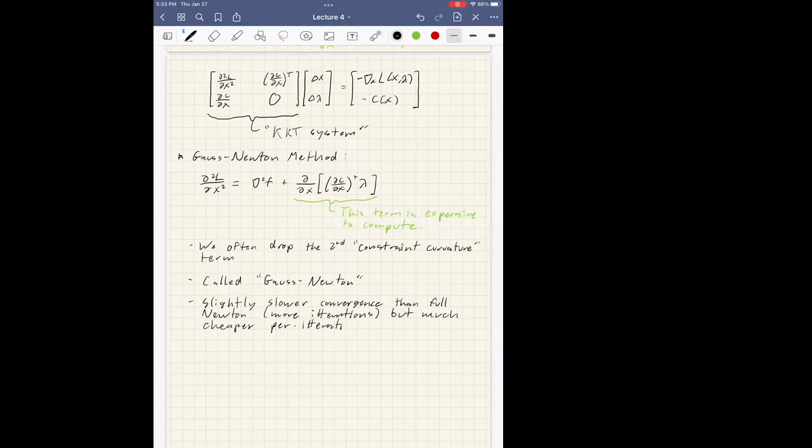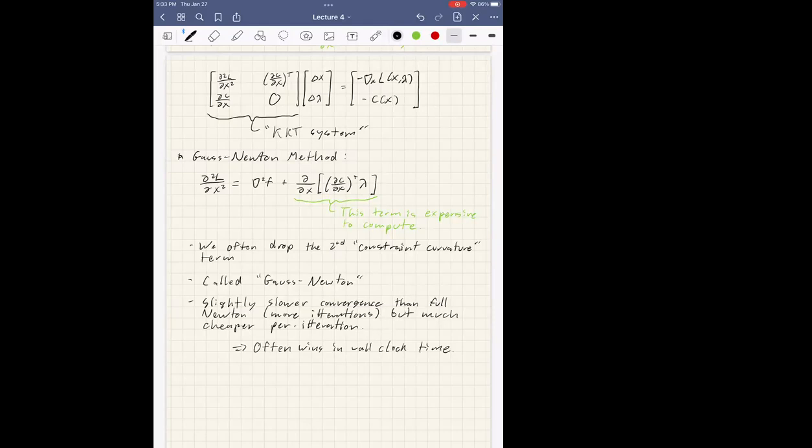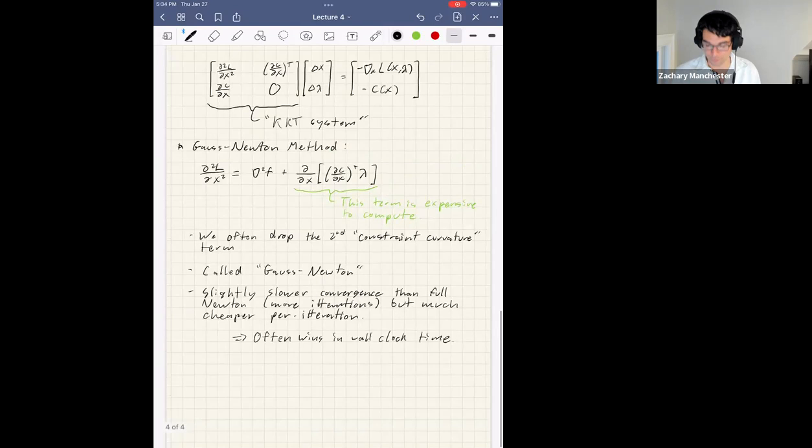What do people generally do with initialization? It seems like it's pretty important for the solver. It is, yeah. This is where you get into voodoo-y, dark art sort of vibes. When you're doing this on non-convex nonlinear problems, like we usually end up with in these robotic optimal control problems, the initial guess problem is huge. Generally speaking, this is where you have to use all of your intuition and engineering insight to give it a good initial guess. The better you can do with the initial guess, the better these techniques all work, because they're all local search techniques, right? You will get experience with this. But for now, let's just say it is a bit of a dark art, and you have to do the best you can engineering a guess before you plug it into these methods.